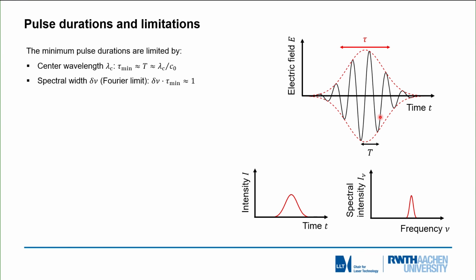In frequency, this of course depends inversely on the time domain. If you look at it from the Fourier point of view, a rather long pulse will correspond to a rather narrow frequency spectrum, and vice versa. If we increase the frequency spectrum, we get shorter pulses, narrower superposition in time. So the spectral width corresponds directly, very simply, with the pulse duration.